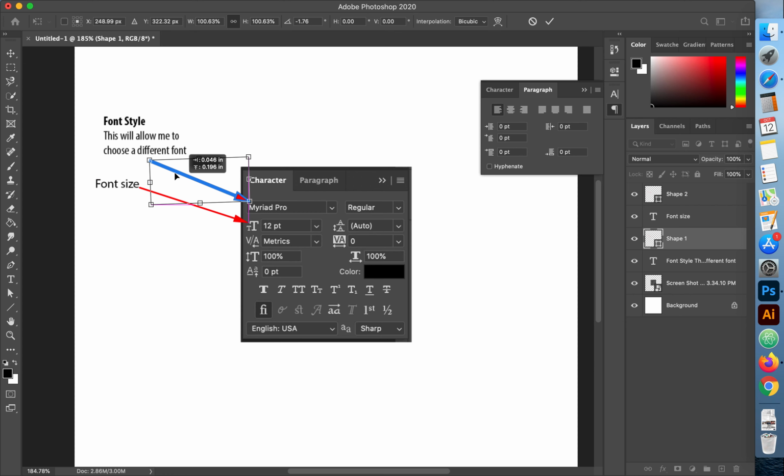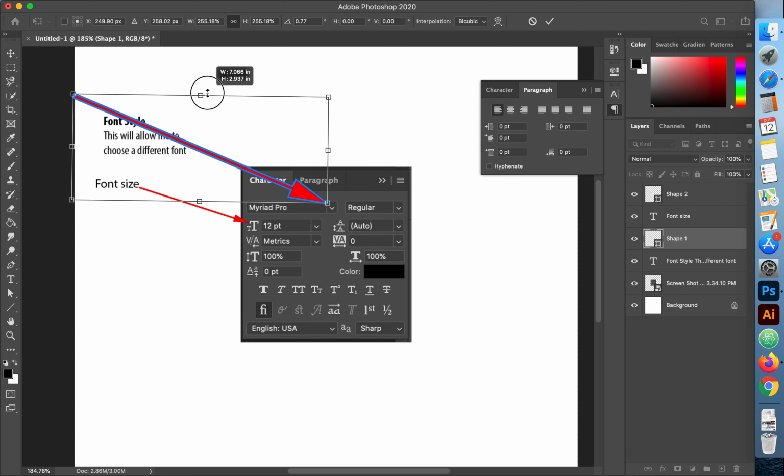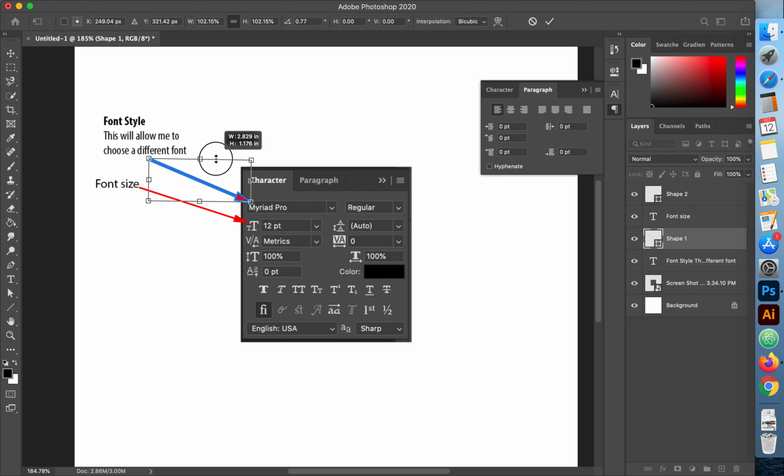But if you click on the Move tool, and then Show Transform Controls, you'll get the ability to move that around. So if I rotate this, you'll see I get the rotation arrow on the outside of one of the corners. This will just let us scale it up and down.